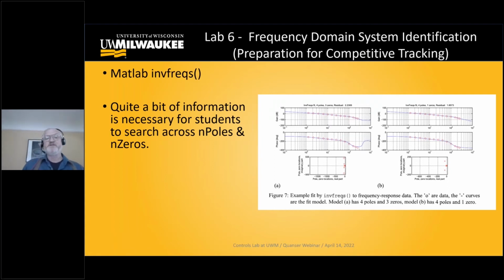That, of course, introduces an additional pole at the origin, and we'll measure the frequency response of the system, voltage to position, across a range of frequencies that's sufficient to capture the resonant mode introduced by that belt.